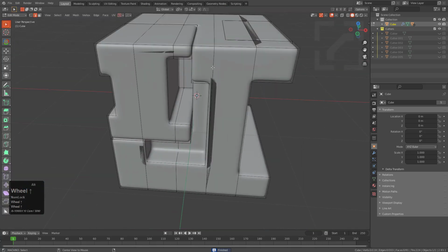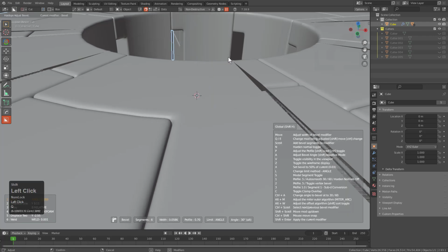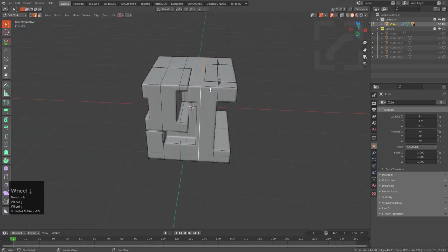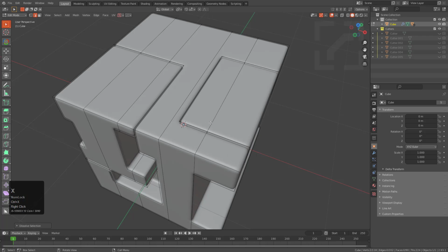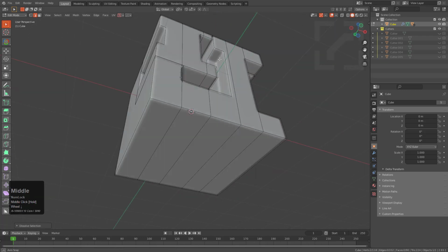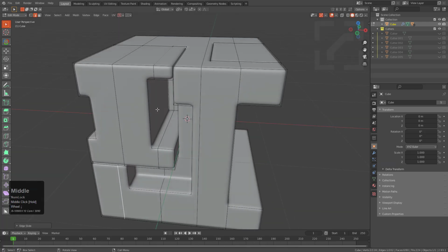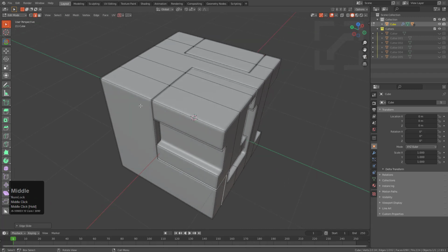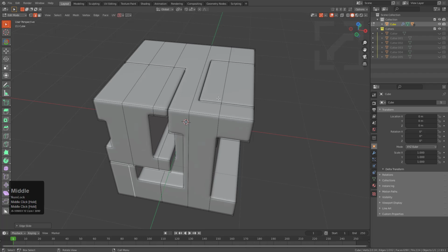However, we can always tab in edit mode and just look at our geometry to see what is getting in our way. So we could slide this edge over, we could go under bevel and actually adjust the amount of bevel that's happening. But instead of adjusting the amount of bevel, I like to get in and perform topological examinations. For example, this edge was redundant and wasn't needed to be present, so it's causing some issues. This one is too close to this particular edge, so it just needs to be slid over. So sometimes instead of redicing, as you saw me doing, which could possibly lead to a crash, sometimes it's just a little bit of examination as far as why Dice doesn't work out.